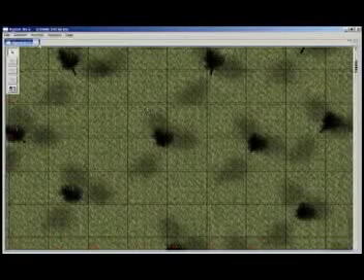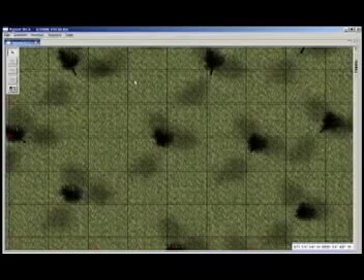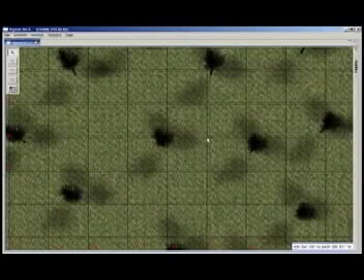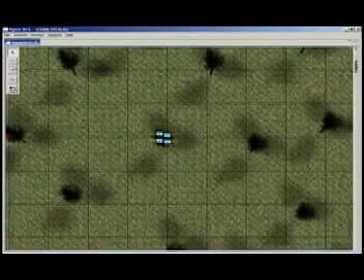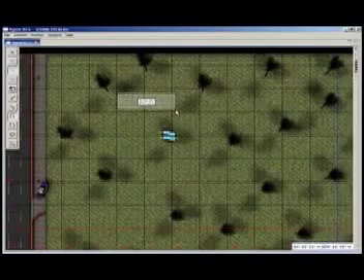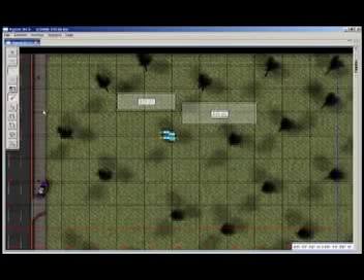Another type of agent system we added was a type of auctioning system. This system will take multiple AOIs and multiple vehicles and determine which vehicles should search which areas based on the vehicle's shortest path to the AOI and the search radius and speed of that vehicle. These values are all used to compute a bid from each vehicle for each available AOI in the arena. The auctioning system then takes all of these bids and determines the most cost-effective way to assign the vehicles.